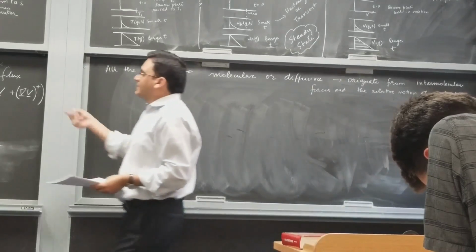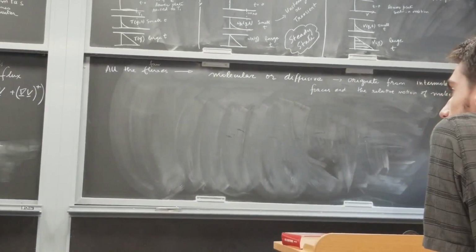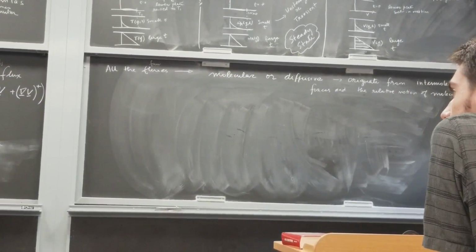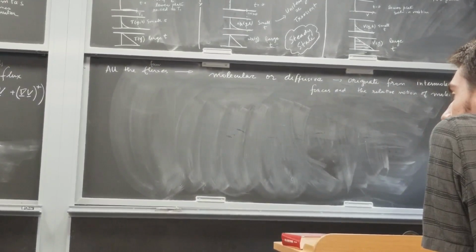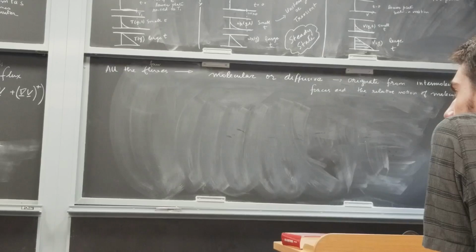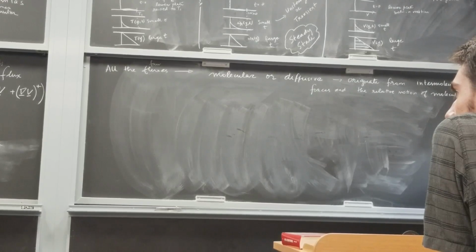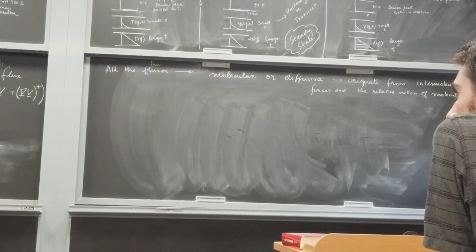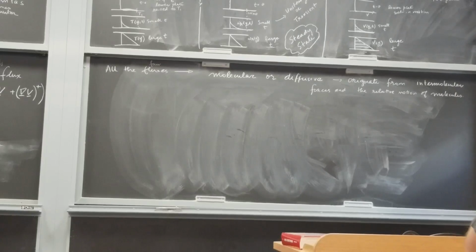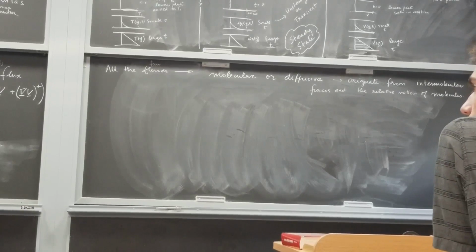So for example, in fluid mechanics, when I move the lower plate, all the molecules from the liquid right next to it are carried away with the same velocity. In fluid mechanics we call this the no-slip condition. But as they are being carried away, they'll try to transfer some of this momentum to the next layer, and the next layer, and the next layer. And that transfer is not very efficient.